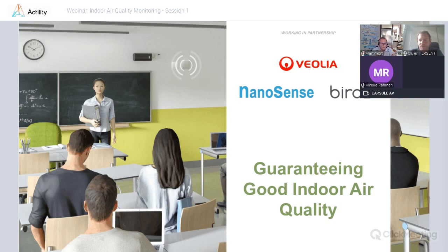Then there was a question on benefits of LoRaWAN compared to narrowband IoT and Cat-M. Clearly, there are two. One is power consumption. There is about 1 to 20 ratio in the power consumption between LTE-M and LoRaWAN, and about 1 to 10 between LTE-M and narrowband IoT. So this is absolutely huge. So I think all the sensor manufacturers here in the room, they know exactly why they've done LoRaWAN.